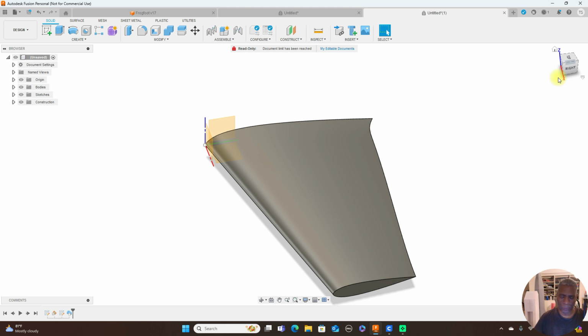Now, the ones that you'll see me use a lot are the spline and the line. I'll use a circle once in a while when I do the wheels and things that need a circle, but normally it's just the spline and a line. Two very important commands there. And using forms, what you'll use the most is the cylinder and the box, to get all the shapes you need in forms and to be able to manipulate those around to get the shape that you need.